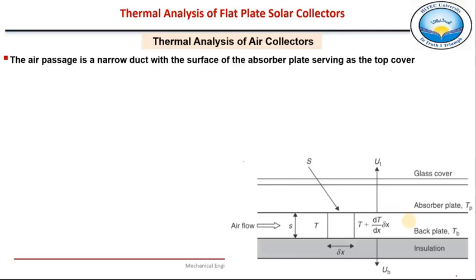So there is no fin efficiency, and also there is no bond conductance or bond resistance, right? Because there are no pipes which are welded to this plate. So air is directly coming in contact with this plate, right? This simplest type of air solar collector, we shall analyze its thermal analysis, but we shall not be